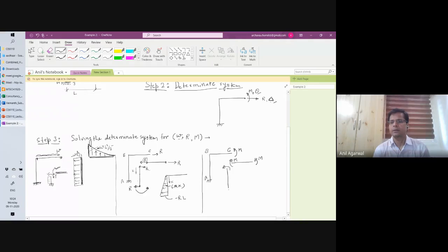Fine. And now this member is not in equilibrium. So of course, the boundary condition has to balance that in the opposite direction. Okay, so this is the free body diagram. You don't need any other forces or moments to make it in equilibrium. The values are all M. Now if you look closely, which side is the tension side in each member?